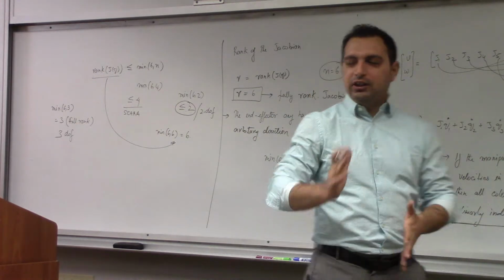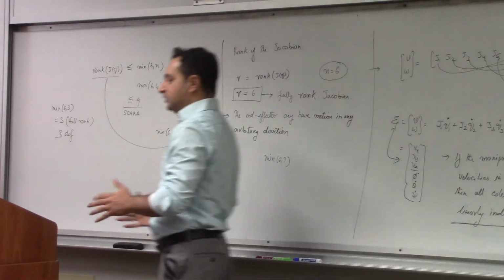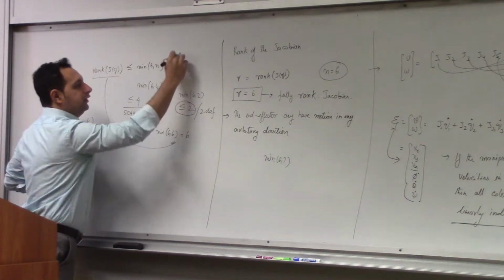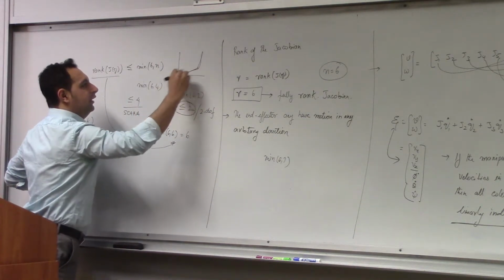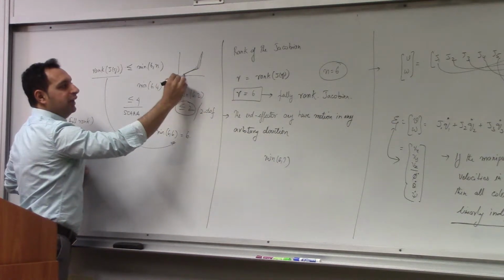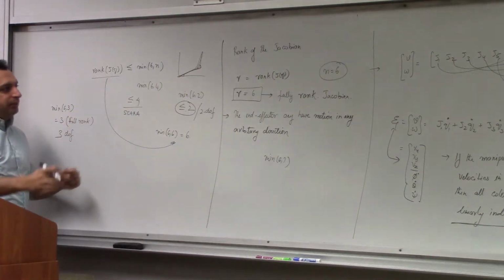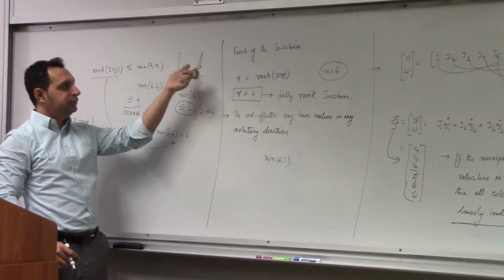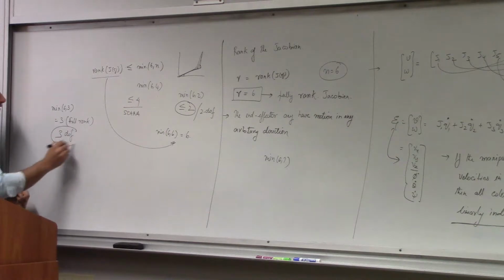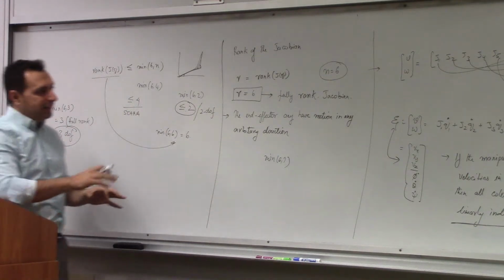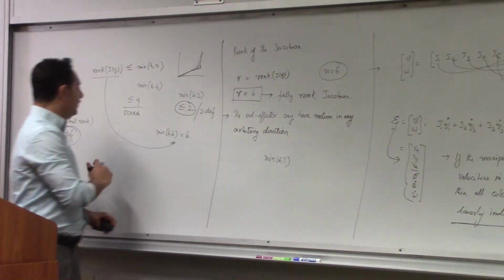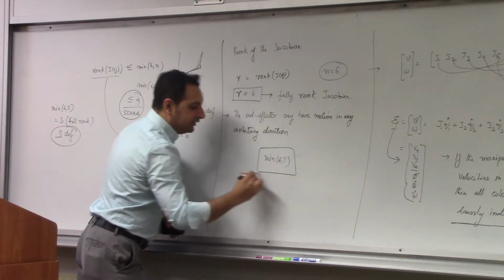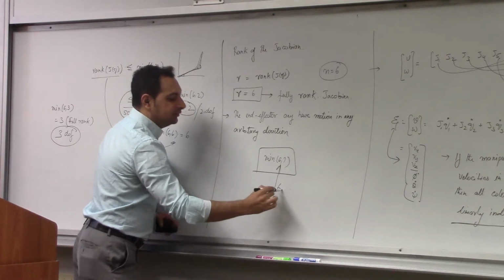Let's go back to the first class. We discussed this. See, I have only 2 degrees of freedom, right? This is the manipulator. So the rank can be only 2 because I have only 2 joints. I cannot have a third rank because I cannot generate motion along the third direction. I can only generate motion along 2 dimensions. Same thing with 3 degrees of freedom: the maximum number of directions I can move in is 3. Same applies to 4. But when I go to 7 degrees of freedom, why is the maximum rank limited to 6?